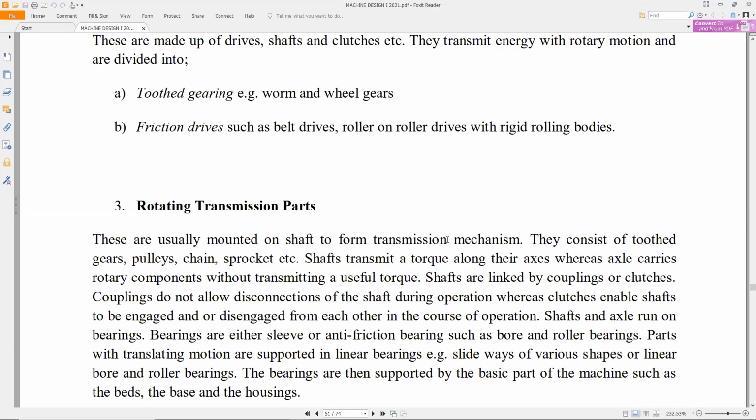And usually in the engine of a vehicle, you see that the crankshaft, which is a shaft carrying the power coming from the engine, can transmit that power to the wheels of the vehicle through the clutch. Usually in the gearbox of the vehicle, we have a shaft there. So there is a crankshaft coming from the engine, and another one in the gearbox, and in between them is a clutch. So if you want to send power from the crankshaft to the gearbox, which will go to the wheels, you need a clutch to be able to transmit the power.